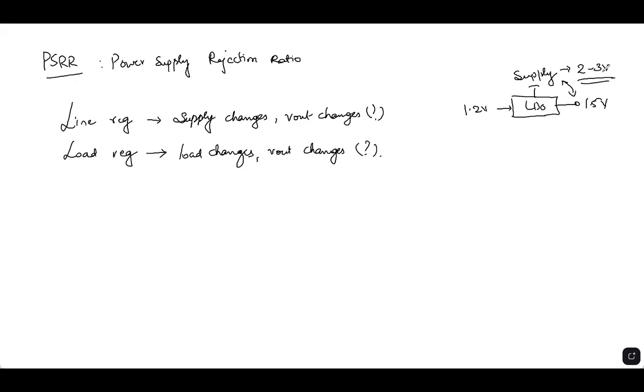At 2 volt, maybe everything is in saturation. At 3 volt, some of the devices internally may go out of saturation to, say, linear region. Cannot be avoided, right? Of course, our job is to make sure that all the transistors are in saturation across the supply range.